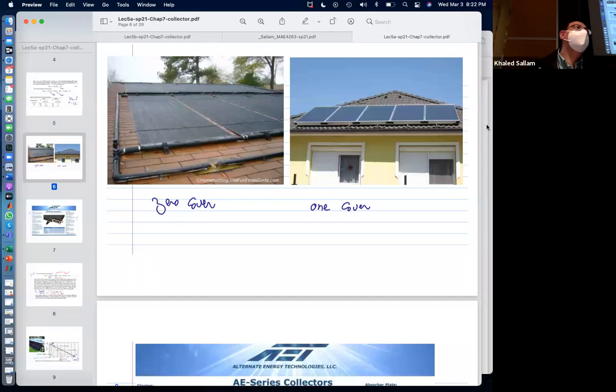No, it will not pop the pipe. It will get hot enough to the extent that the losses are equal to the incident radiation. It takes a certain temperature, you hit this point, and then you basically radiate back everything. This is the temperature that the car seat will reach when you close the window, and you don't let air in or air out. The air will get as hot as it can and stops.